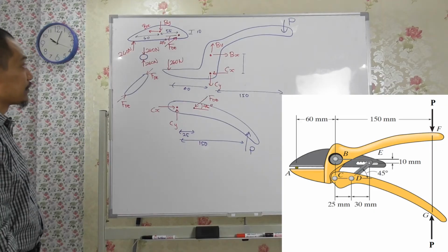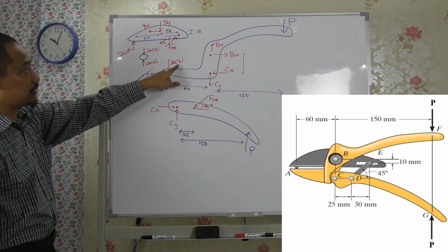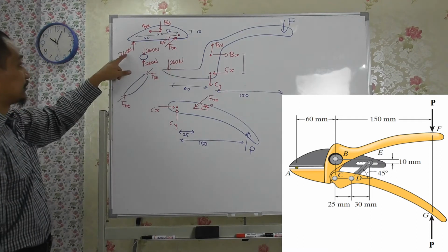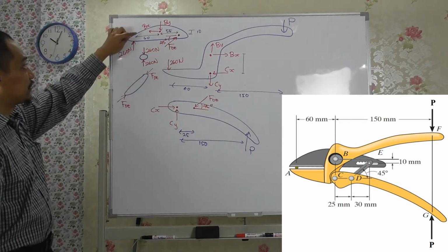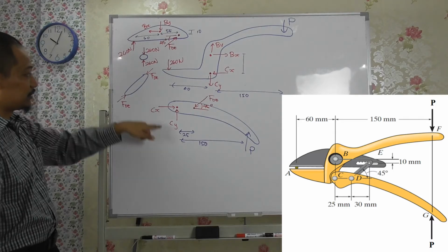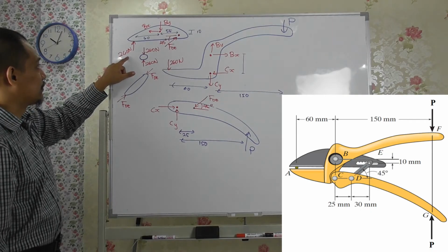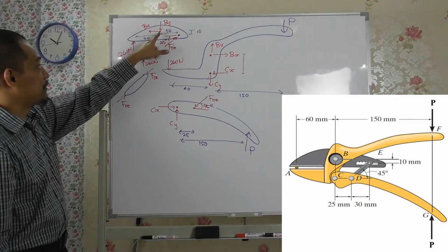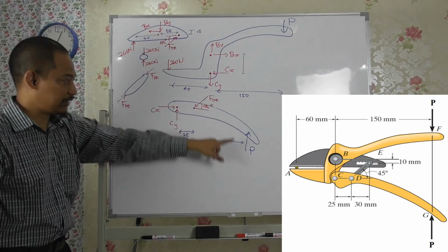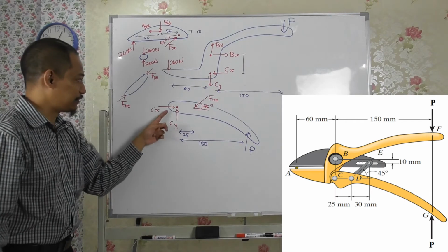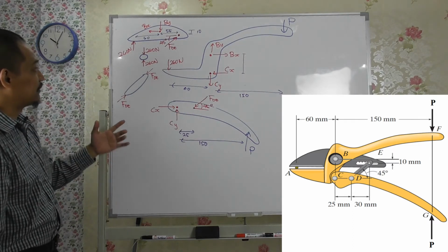So the same there. And your value is from here, 260, right? So either starting from this 260 to get to that P, or starting from this 260 to get P, either that one or this one, right? So connecting this thing here to this is FDE actually, right? So from here, can I get FDE? Yes, I can, right? Because if you take moment about point B, you can get FDE. If this FDE is obtained, I get this one. Can I calculate P? You can, right? Because if you take moment here, then you can calculate there, right? So from there I can, okay, then I will use this too.